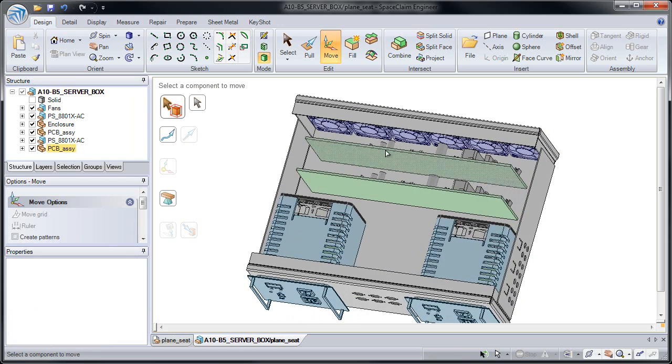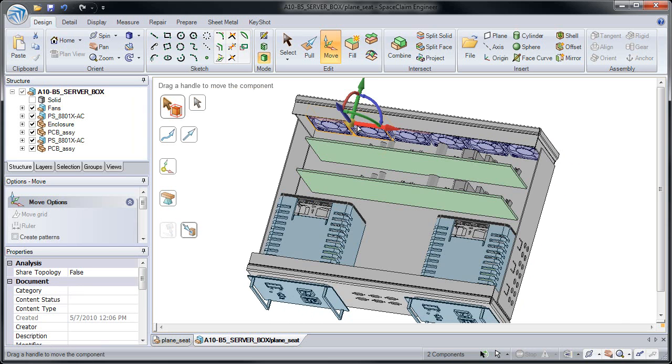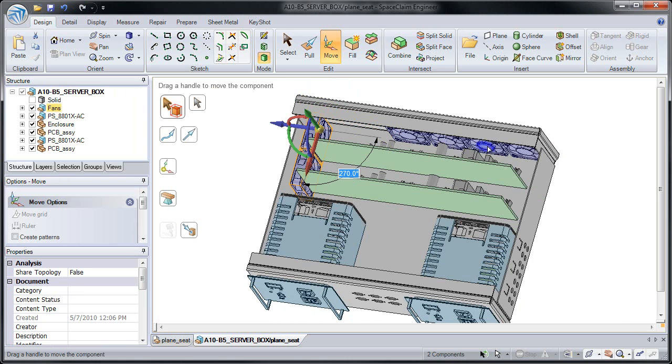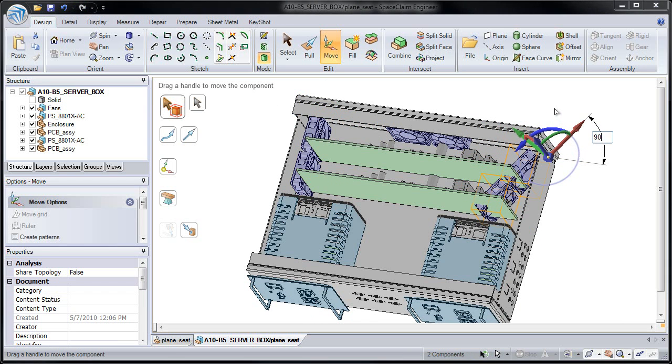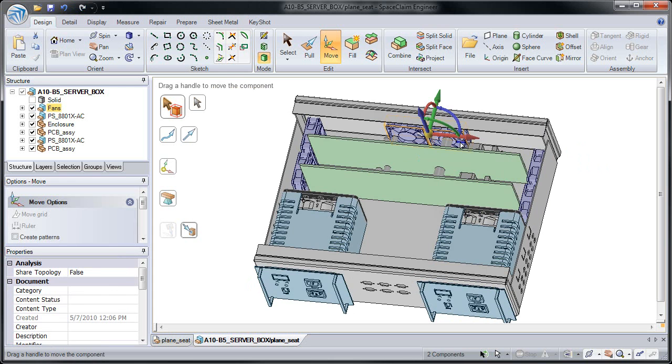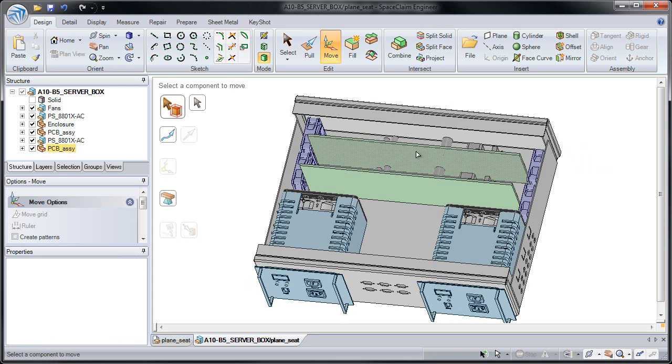By placing our circuit boards vertically, not only will it be easier to run air across them, but it will also be easier for assembling and replacements later on down the road. In fact, by rotating our fans and running the air across them, we could even possibly get rid of one or two and reduce both cost and weight.